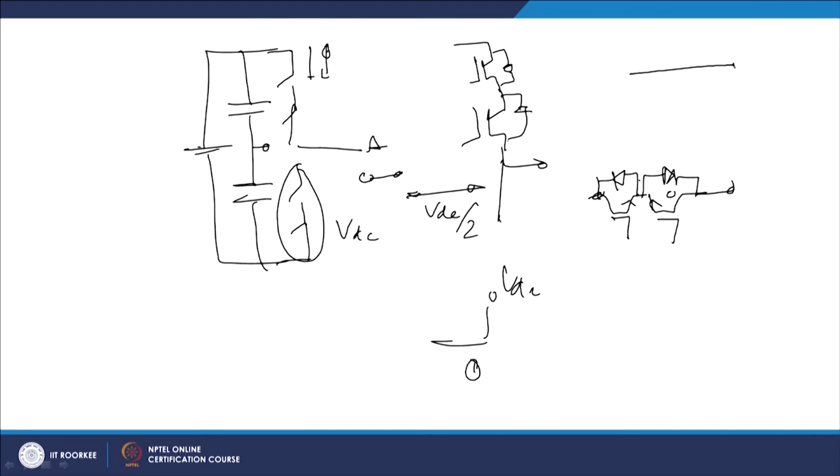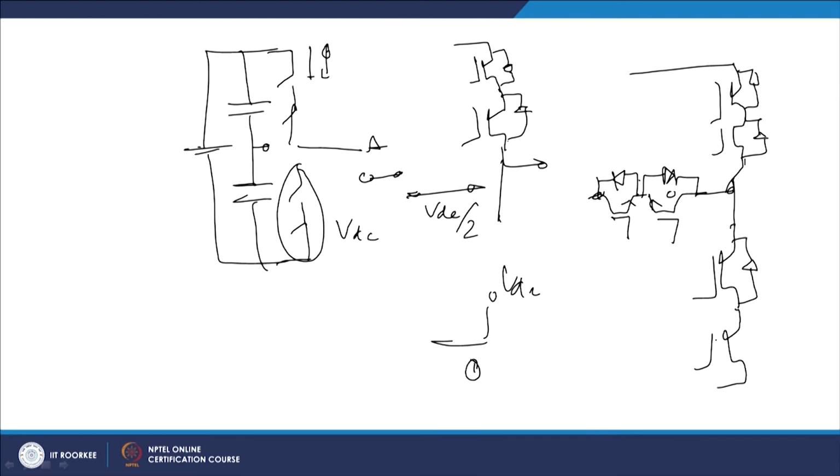So, and above it you have 2 switches. And similarly, when it is connected to the position 3, it will be the same position for 1. So, you have these circuits, but you see that to realize one leg you require 6 switches. So, can we have some kind of redundancy here, and can we not minimize it?